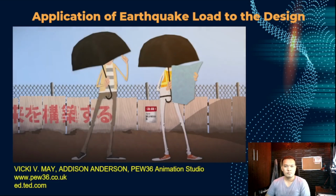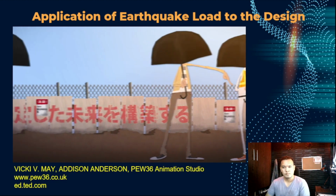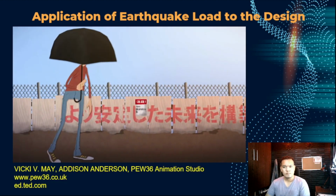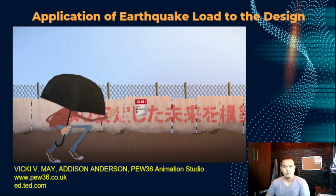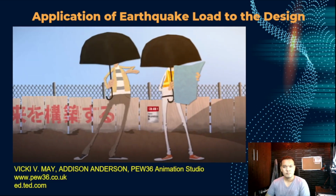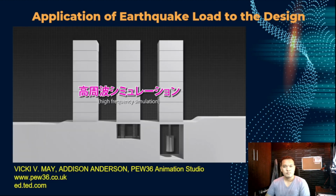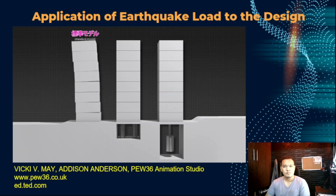Today, engineers work with geologists and seismologists to predict the frequency of earthquake motions at building sites in order to prevent resonance induced collapses, taking into account factors such as soil type and fault type, as well as data from previous quakes. Low frequencies of motion will cause more damage to taller and more flexible buildings, while high frequencies of motion pose more threat to structures that are shorter and stiffer.